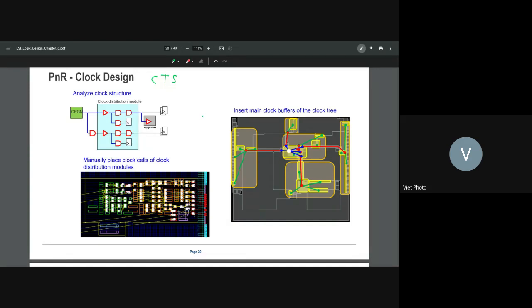So for the part with 3 or 4 levels of logic, let's say I make up a frequency of 1 gigahertz, which gives you a period of 1 nanosecond, and you have a part of only 4 stages. Let's say each stage has 20 picoseconds, so 4 stages is only 80 picoseconds. So 80 picoseconds largely meets the timing requirement of 1 nanosecond, right? Because the max delay of that part can be up to 1 nanosecond and the clock still functions at 1 gigahertz.